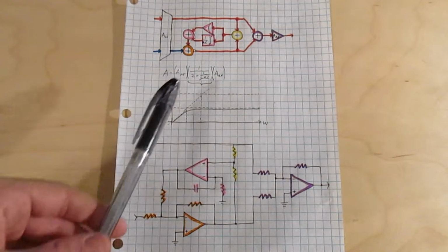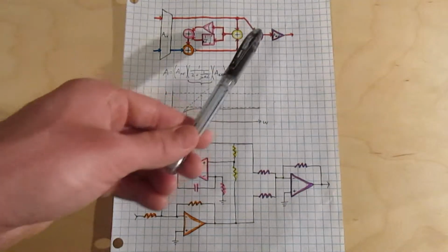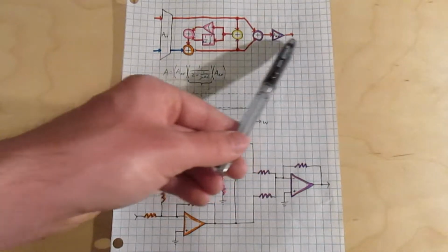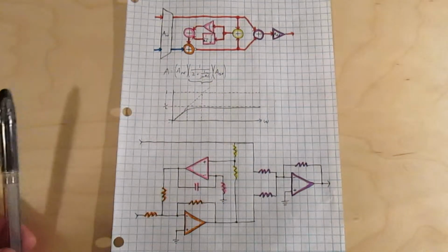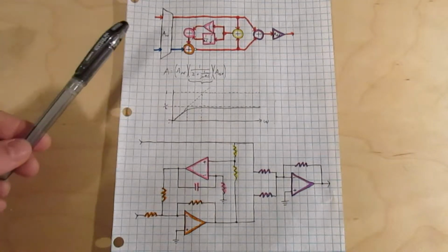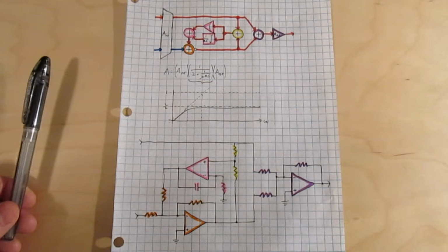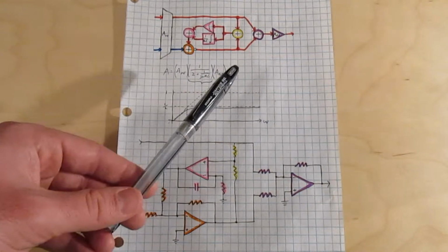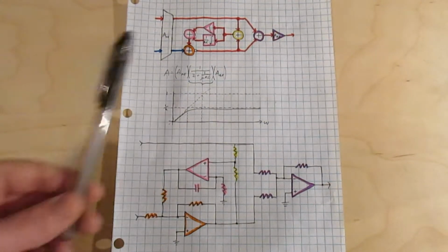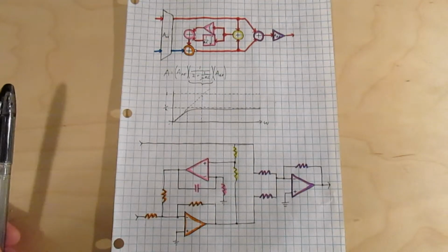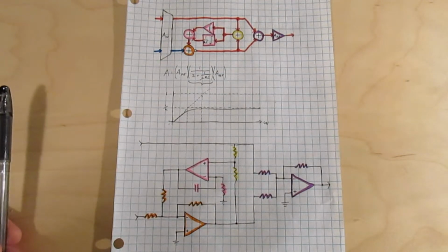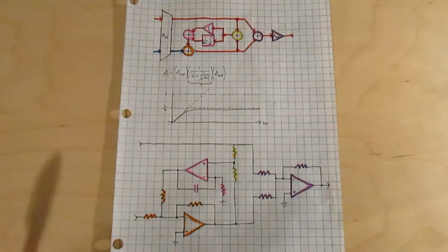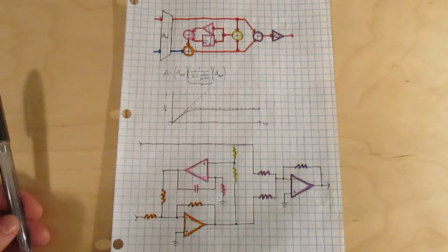But that does make our common mode noise rejection a little bit worse. It's the job of the back end to actually do the rejection of the common mode noise, but it's not perfect, and some of the common mode noise is going to slip out to the output. The job of the front end, aside from being a buffer with high resistance inputs, is to have a higher gain for differential signals than for common mode signals. That way, when the signal actually gets to the back end, the signal-to-noise ratio is already better than it would be. The big problem with this DC offset tracking circuit is that it only reduces gain for differential signals and leaves common mode signals untouched, which means it's actually undoing some of the benefit that the front end is giving us. So for that reason, I would like to have a DC offset tracking circuit that does not reduce the gain.